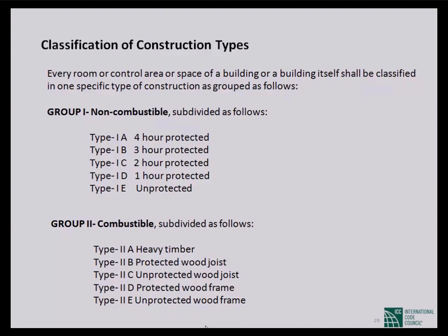So any structure with steel is normally said to be unprotected, but if you wish, you can make it protected for 1 hour, 2 or 3 hours as designed. You can coat steel differently, with low cost to high cost, different types of material.